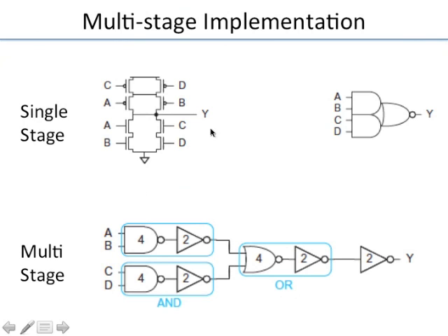And that's really got to do with the fan-in. When the fan-in of a gate becomes larger and larger, that means a series stacking. Here I have a series stack of 2, whereas a series stack of 4, it turns out, is really pushing it. The gate becomes quite slow because you have 4 series transistors. Imagine each transistor is a resistor, and with each resistor there is a small capacitor also. So the delay of a circuit, you can think of it intuitively as an RC product.